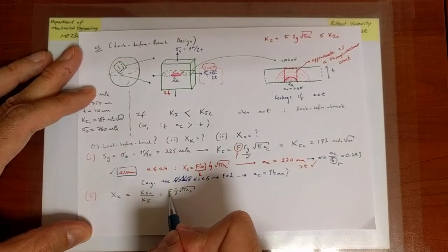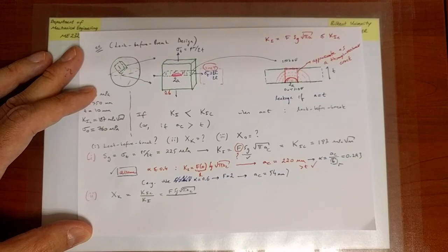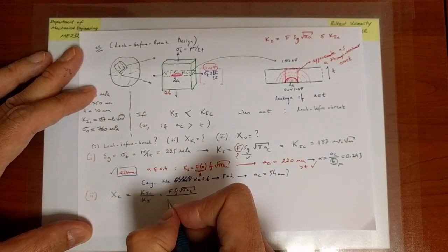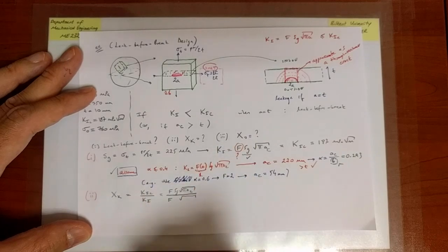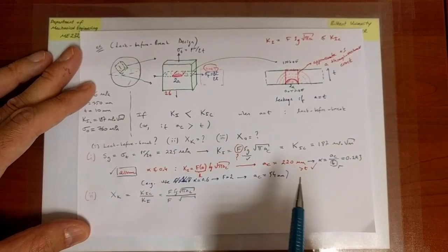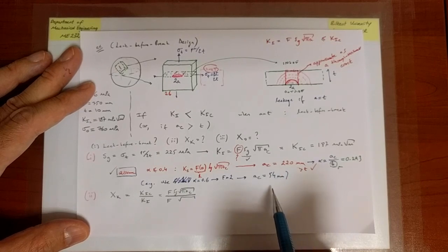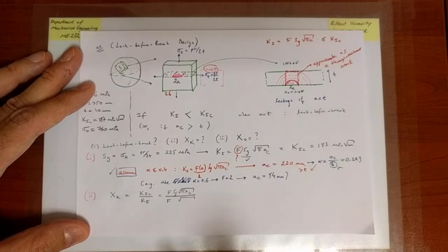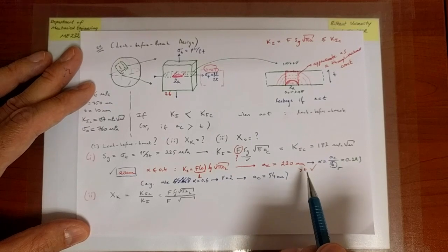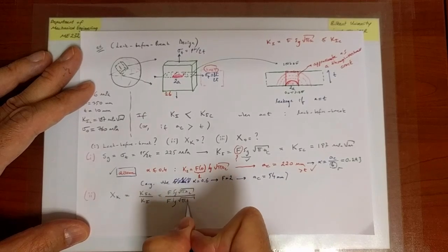Okay? This is the value of F that corresponds to AC. And I will scale it by what I deem to be a critical case. Now, that critical case is F, or K1, evaluated at the most critical scenario towards fracture. Now, I know that the pressure vessel is going to leak before fracture. So as the crack size grows towards T when leakage will occur, the situation gets more and more severe. The severest value of K1 is when A takes the largest value possible. The largest value possible is the thickness value. So the largest value of K1 that I can possibly see in this scenario is at the thickness value.